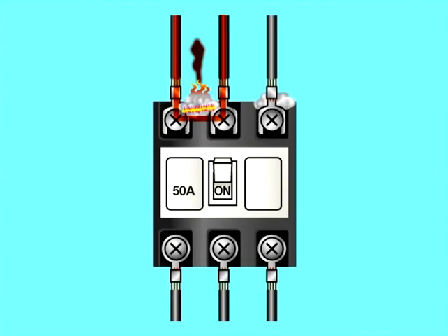Dust can easily accumulate inside the control panel containing the sequence control circuit. If this dust accumulates between the control relay terminal and the MC terminal, electric current may flow through it, generating heat and even fire. This fire may spread to the electric cables inside the panel and, in the worst case, burn out the whole control panel.